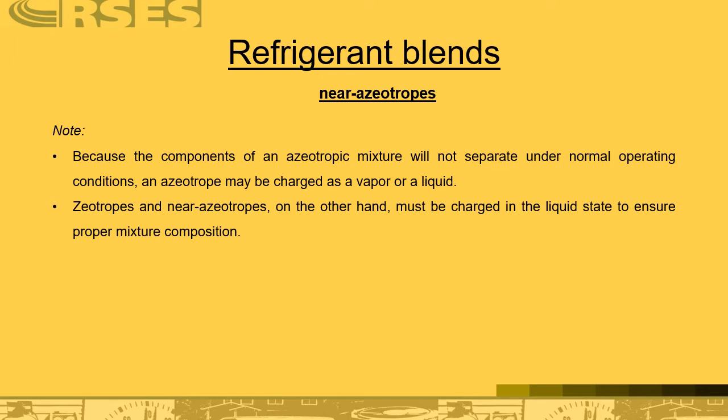Typically, we are going to add liquid after the system factory charge has been open to the rest of the system and the unit operates for a period of time, in order to get our subcooling to the correct charge level.